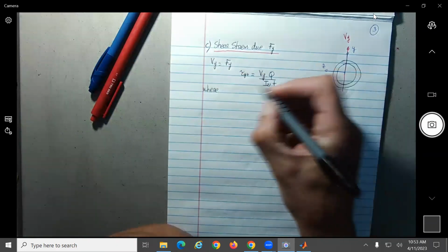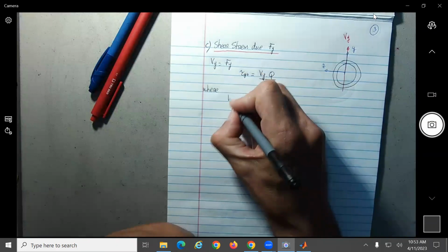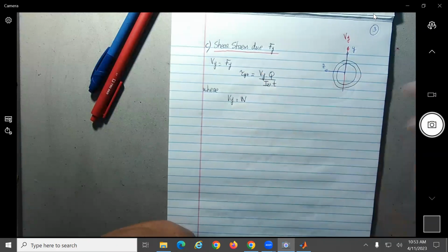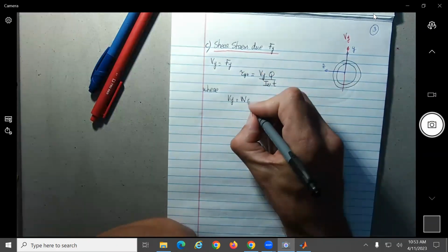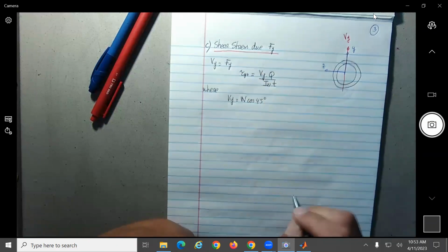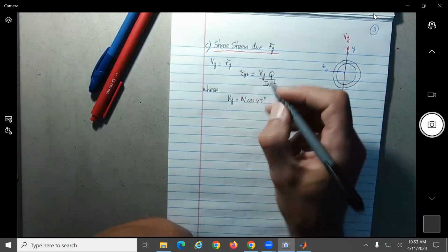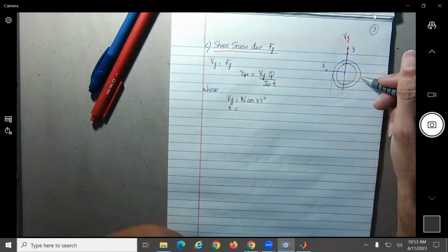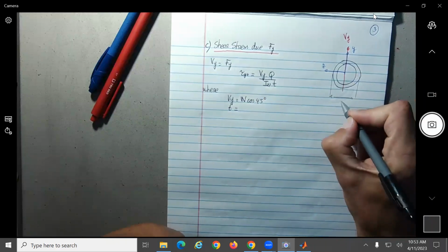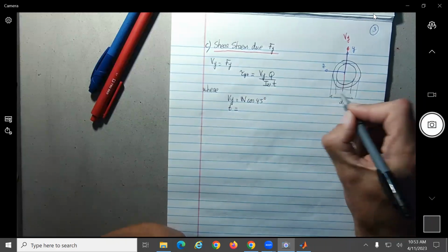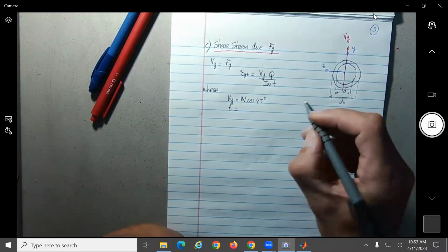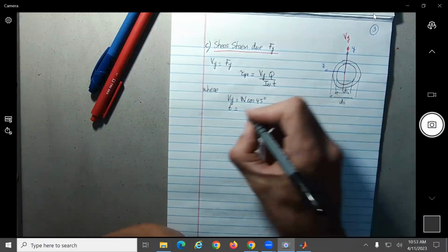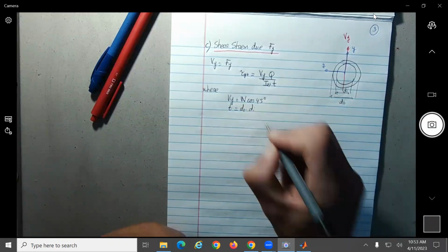in this equation, we know the Vy will be equal to what? W percent 45. Now the Izz, we already have the value, but let me just put the T. What should be the T? The T will be the thickness on this side plus the thickness on this side, no? So you write this should be D outside minus D inside.